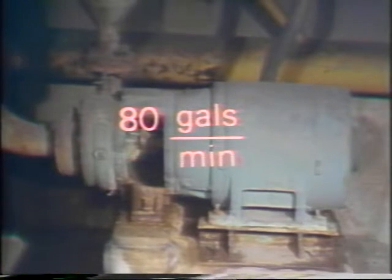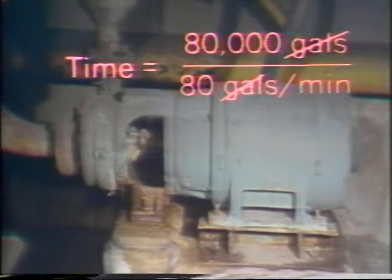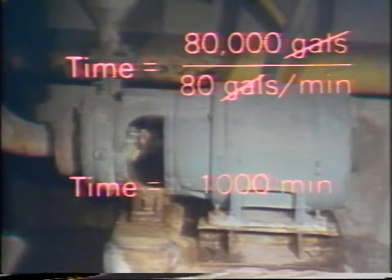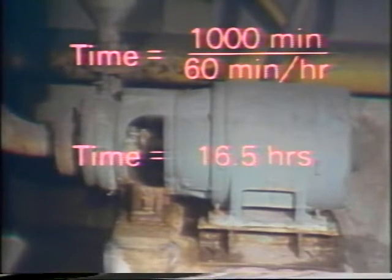In this case, if we divide the capacity of the tank, 80,000 gallons, by the flow rate, 80 gallons per minute, the gallons cancel, and we find that it will take 1,000 minutes to fill the tank. If we want to know how many hours there are in 1,000 minutes, we divide 1,000 minutes by 60, because there are 60 minutes in an hour. We find that it will take a little more than 16 1/2 hours to fill the tank.